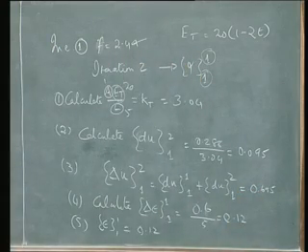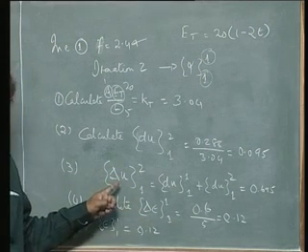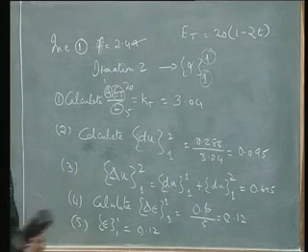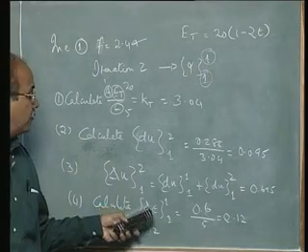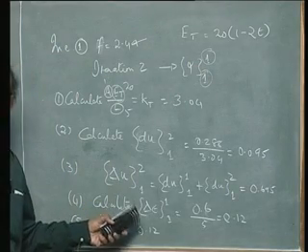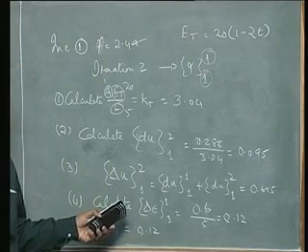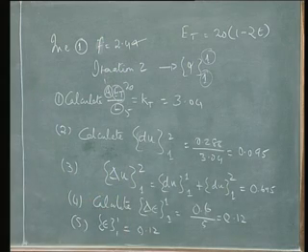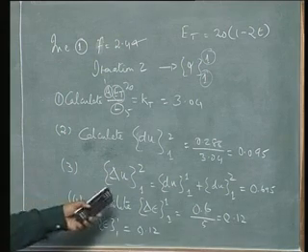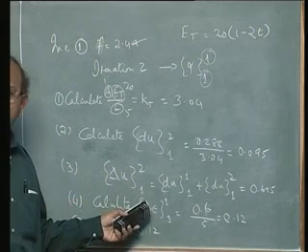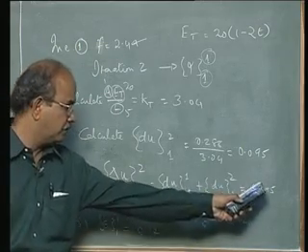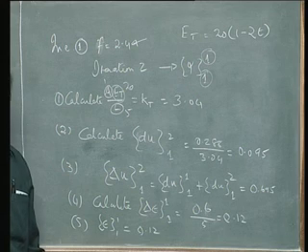It's always a good practice to calculate delta epsilon from delta U. Note this carefully. There is a small subtle point here, that we always calculate delta epsilon from delta U, though for this problem it won't make a difference, but you will notice in the next series of problems that we are going to do and discuss on elastoplasticity, that's going to make a difference. So let us stick to the same procedure. So delta epsilon is now calculated from 0.695 itself.